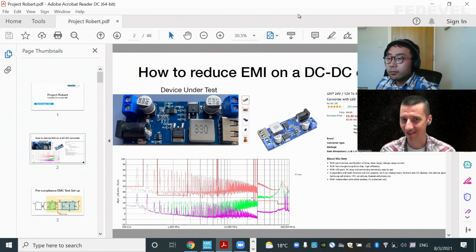So they actually sell a board which is not passing the EMC or EMI test. I haven't tested this one against, say, the home appliance products limit. The limit we show here is a limit for automotive. Yes, it's for CISPR 25 class. And for home, it's a little bit higher. Yes, but I'm pretty sure it will fail the home appliance limit as well if it's tested against it. Yes, good to know.